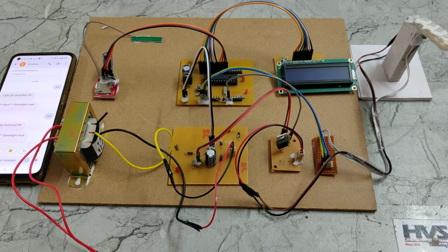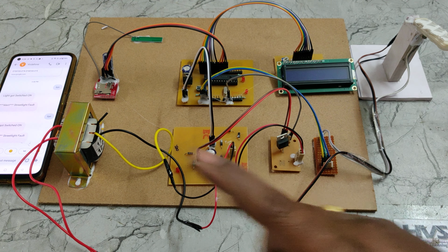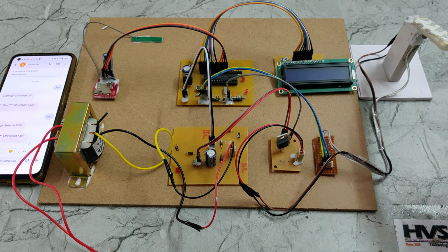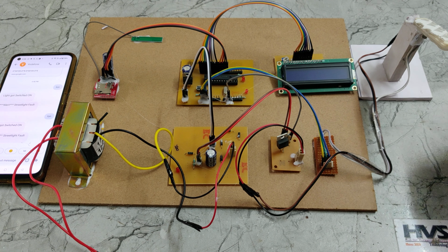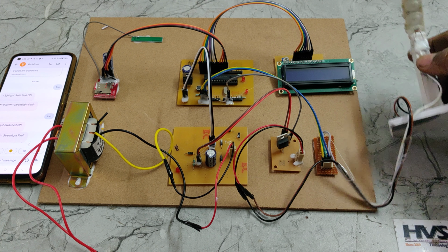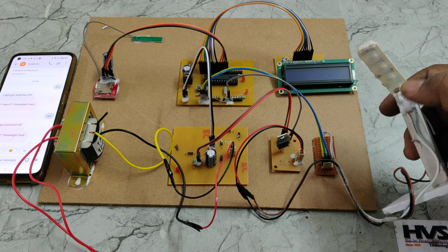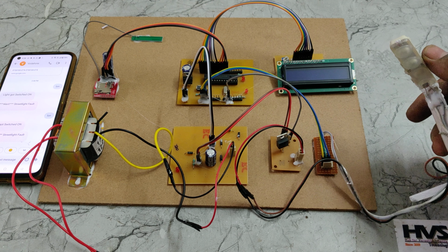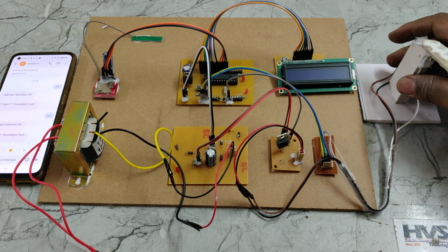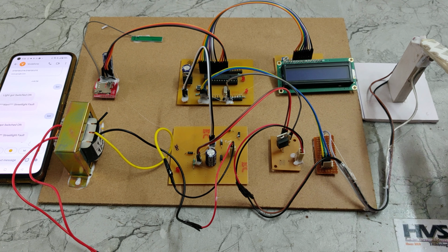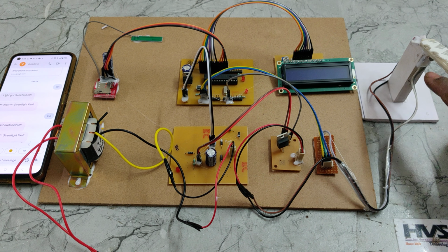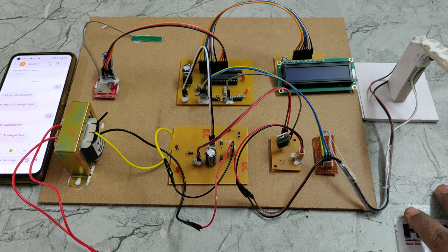And the next feature is, if any fault occurs. When you send a command to the system to turn on this street light, the system will turn on the street light. But this LDR sensor will check the status of the LED, whether it is in on state or off state. So our microcontroller will check whether the street light should be on or not. Once we turn on the street light, again in a closed loop manner, the system will check the LDR input. If it is getting the input from the street light, then it is a normal condition.